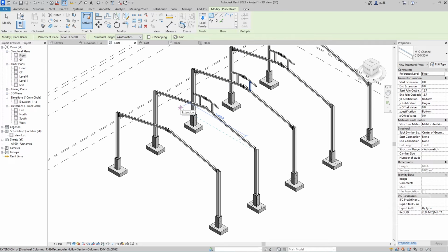While manually creating the bracing system or the rafter of the warehouse, we're going to use the BM command, but to make it easier, we're going to use the peak line as our main reference for creating the best position of our beam, or in this case our rafter.